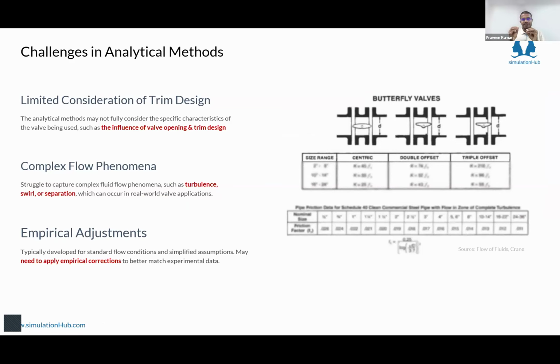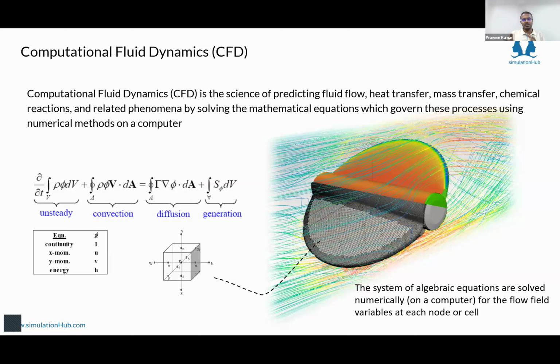Your trim design is changed, so how it will reflect in the formulas. So that is a challenge. So then comes the CFD or numerical method. CFD is nothing but you're solving the Navier-Stokes equation, mass, momentum, and energy equations in the fluid cells.